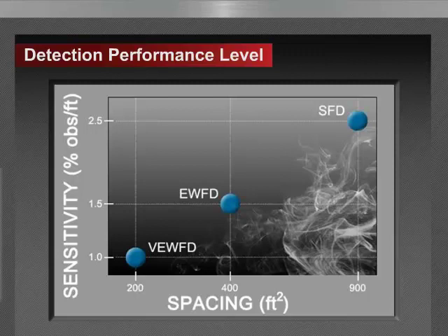Yeah, so if you look at that table in NFPA 72, it suggests the derating factor based on the airflow or air change rate. In the case of aspirating detection systems, and also beam detection, it refers to manufacturer's guidelines. So it has the exclusion, and in that respect refers to the manufacturer's guidelines.